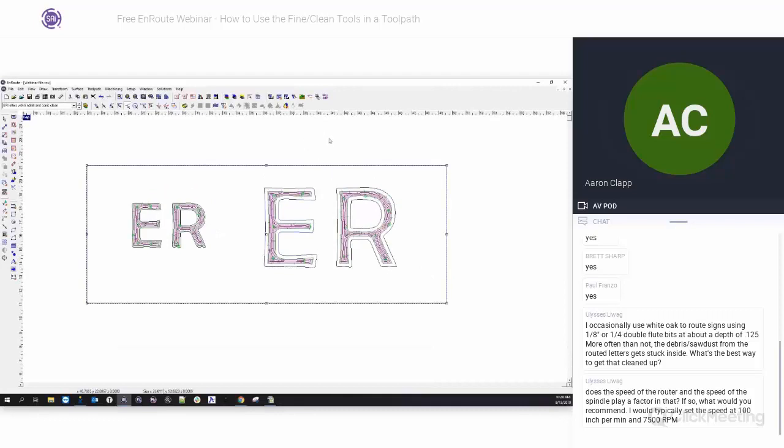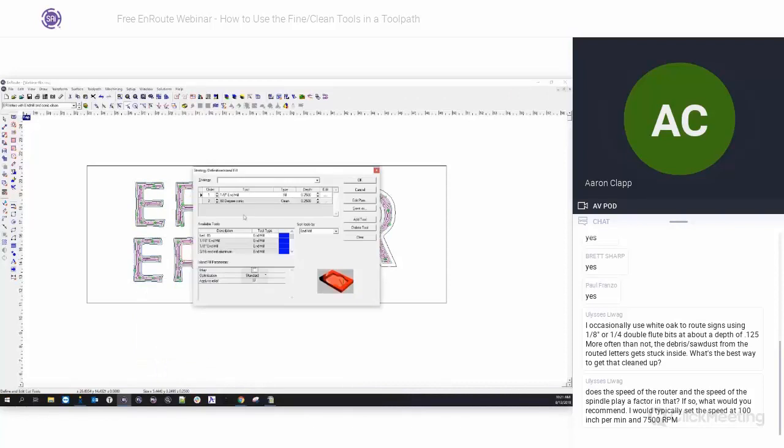So the idea here is that instead of having the letters stand out, I want those letters to be pushed in. But I don't want that weird thing that can happen when you use a conic tool. If you run the edge of the conic, you get a little pyramid shape in the middle where the tool didn't reach. In fact, I think we can just replicate that here so we can take a look at it so you all know what I'm talking about.